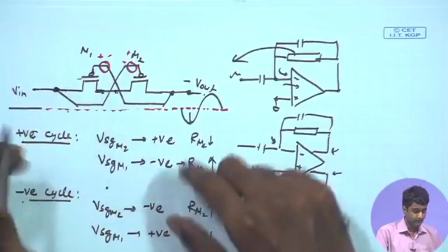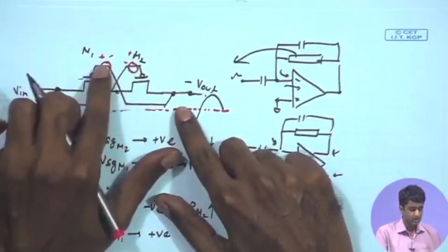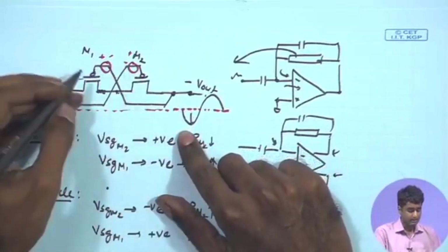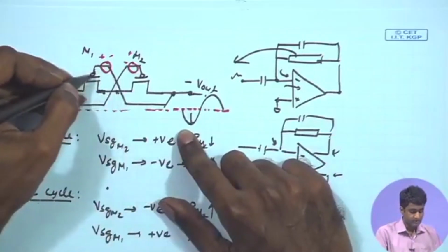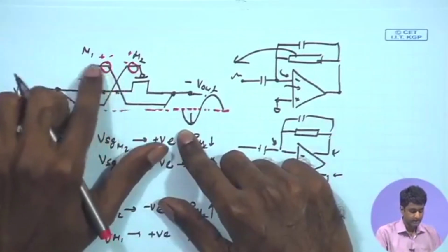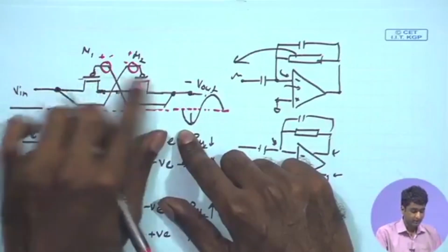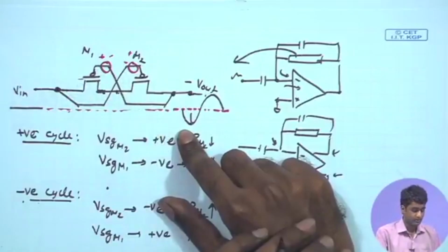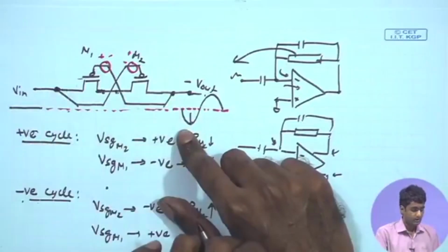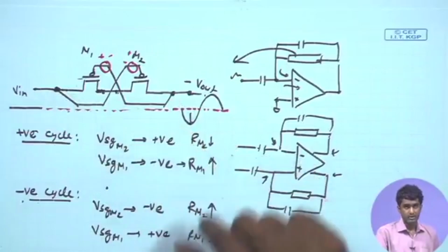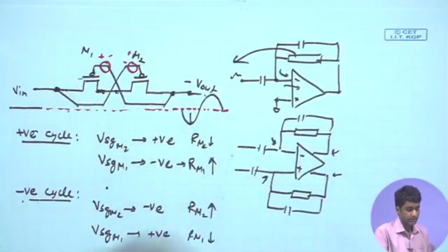So, basically if I insert an additional voltage over here such that the transistor staying off has an additional VSG drop, that can help us in reducing the overall resistance across the switch. That is one way through which we can control the overall resistance provided by this device.